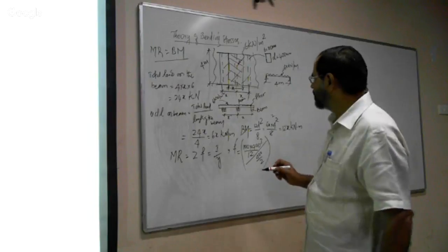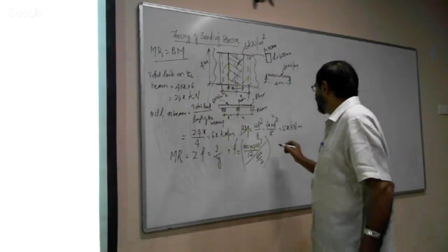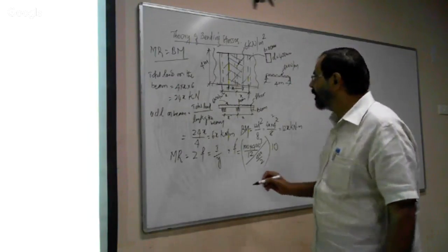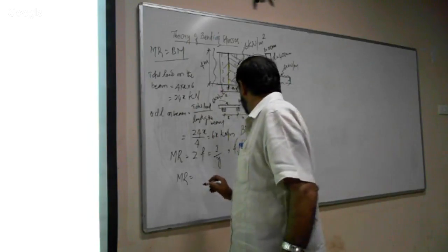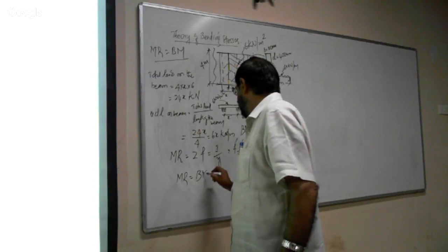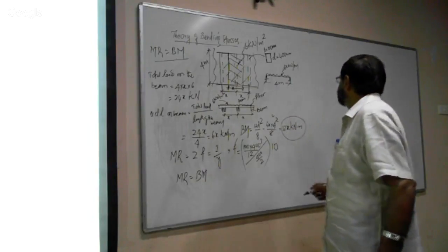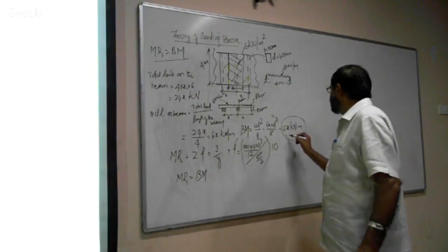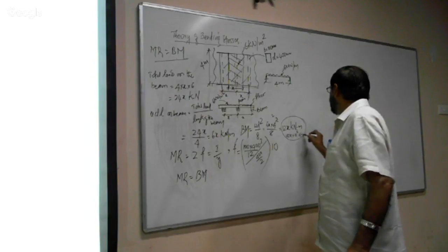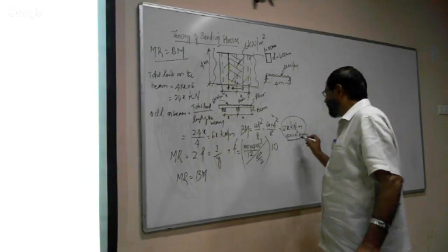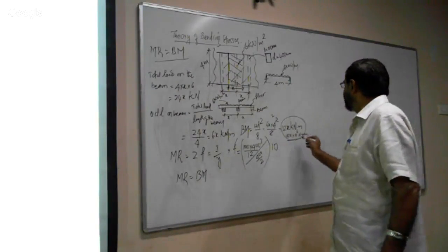Now the stress is given in the problem, limited to 10 newtons per millimeter square. Now the moment of resistance is equal to the bending moment. So equating this, the bending moment is 12 x in kilonewton meter, that is 12 x into 10 to the power of 6 newton millimeter. We equate this and this, so we get the value of the only unknown here, x.